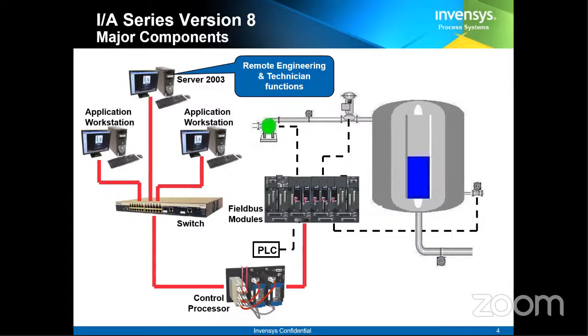See, this processor you are talking about is not part of the DCS system. It is part of the smart transmitter itself. This is a complete single module. It comes as a single device, and this device is supplied by any vendor. Maybe it is made by Honeywell, Foxboro or ABB. There are a lot of players out there in the market.